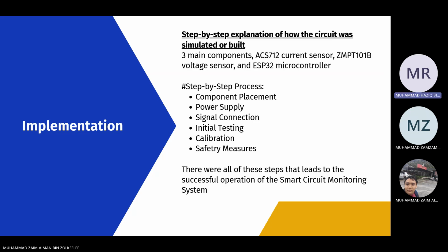The last one is safety measures. Of course, when we measure AC voltage or current, use isolated sensors to avoid direct contact with the high voltage line.